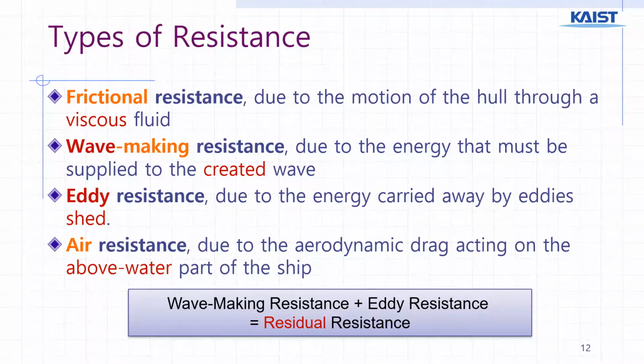So we can use this additional small contribution. The major part is estimating frictional resistance, wave making resistance, and eddy resistance. And the latter 2 parts, wave making and eddy, come into the residual, as Froude assumed 150 years ago.